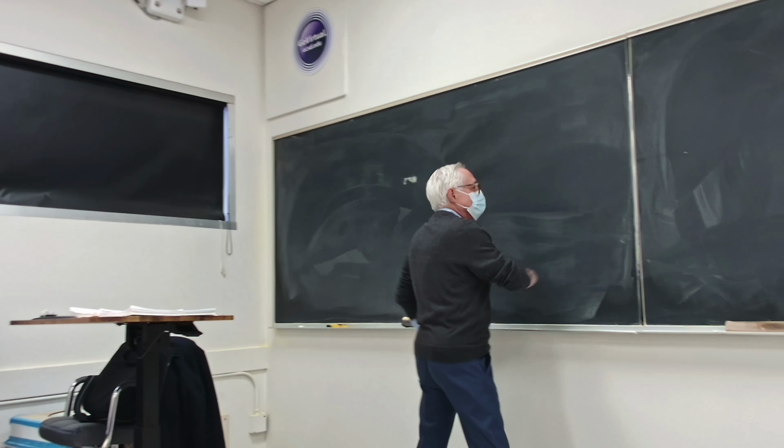Therefore, if you know your condition here, imagine, of course you know, because you are given that I have a saturated liquid at such pressure. You go to the saturation table, you read everything. Then you want to find what is my final state at a pressure much lower than that.